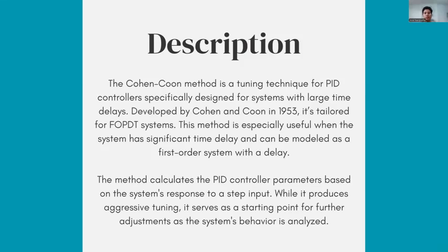What makes this method particularly valuable is that it provides an aggressive starting point for tuning by achieving a quarter amplitude damping response. It ensures quick disturbance rejection. However, this also means that additional fine-tuning may be needed to balance performance and stability.